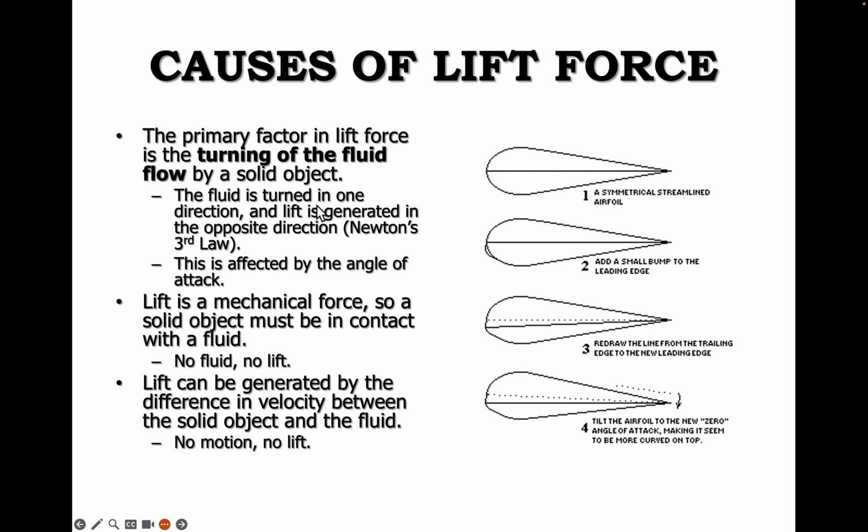With the turning of the fluid flow, the fluid is turned in one direction and lift is generated in the opposite direction, which is Newton's third law. This is affected by the angle of attack of the particular object in the fluid. Lift is a mechanical force, so a solid object must be in contact with a fluid in order for lift force to occur. If we don't have a fluid, no lift force can occur. This is why in space, because there's no fluid in space, no lift forces actually occur in space.